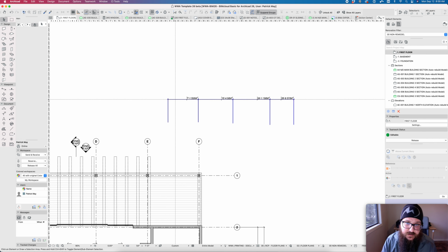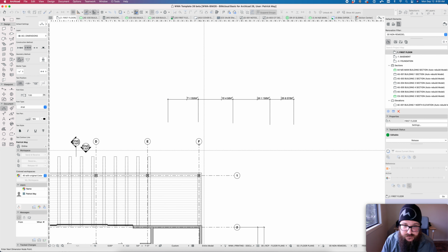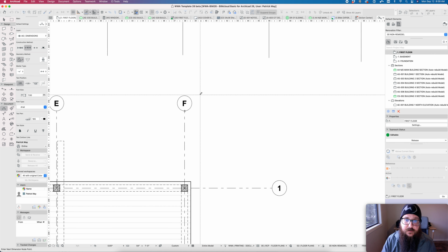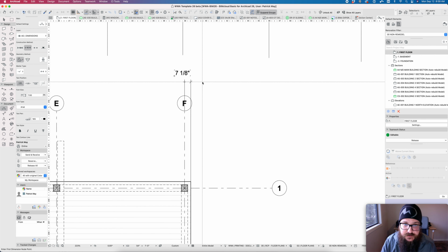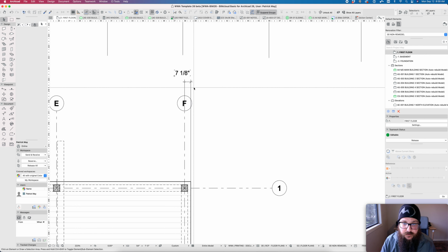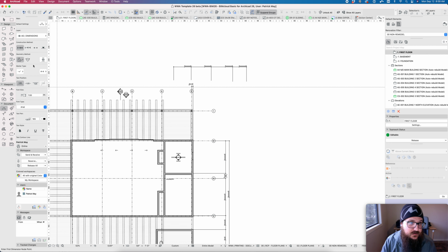We don't annotate that way, but we might need an open circle here indicating center line, and then that open tick mark here indicating face of stud. So by adding that dimension here, I can then have that open circle and that tick mark. I can then eyedrop this dimension type, switch to the open circle, and essentially piece this together as individual segments.